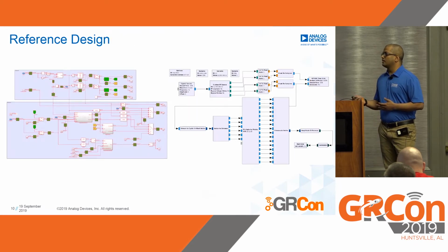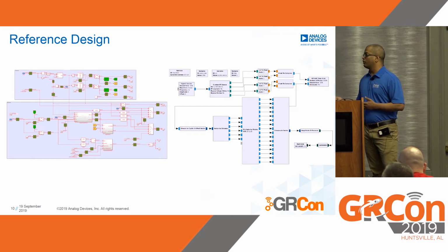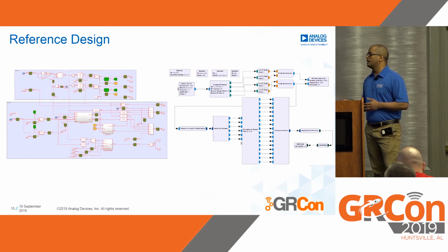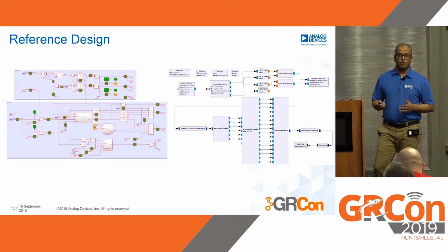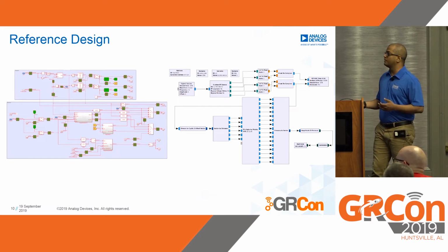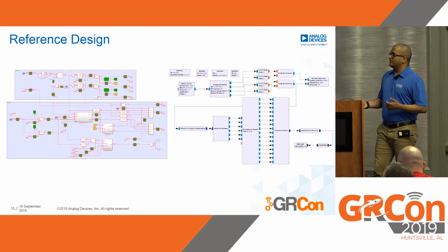So some more details regarding the HDL code that we generated using the Simulink HDL Workflow Advisor workflow and the GNU Radio flow graph that actually implements the fractional delay algorithm. What we see here is we write a value to an AXI register, and that kickstarts the process of sending a pulse waveform. The pulse gets accumulated over time, and that forms the indices going into a lookup table. The lookup table consists of samples from an oversampled Zadoff-Chu sequence. That waveform is sent to the transceiver, and using the RF loopback, it is fed to the receive input port of the transceiver.